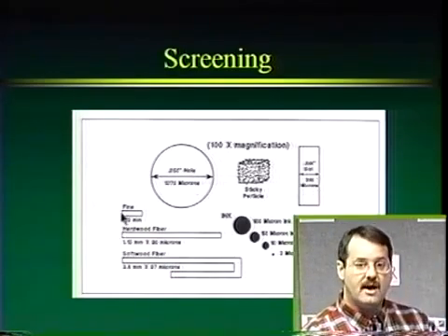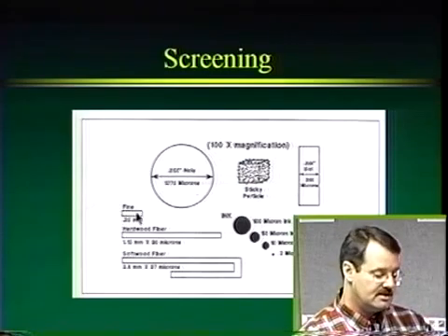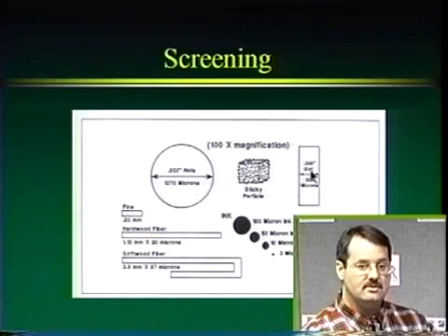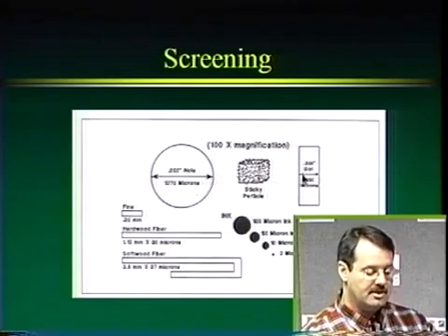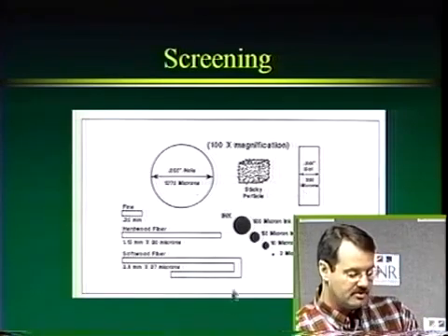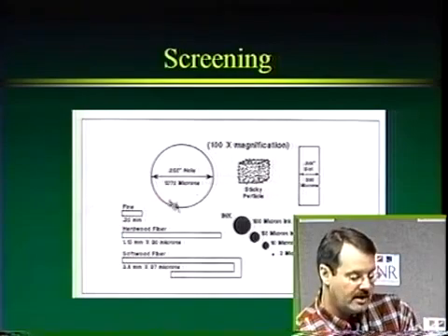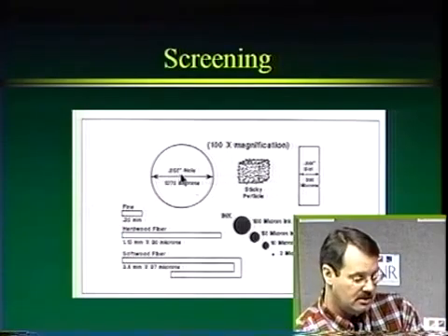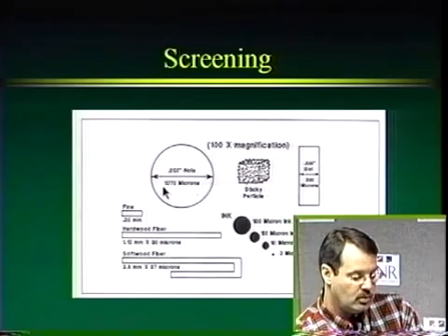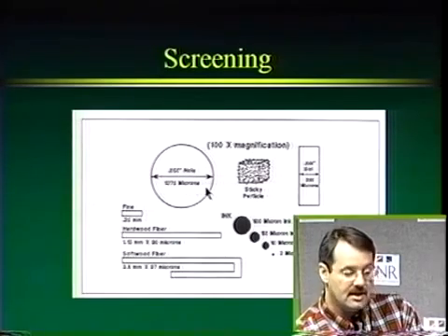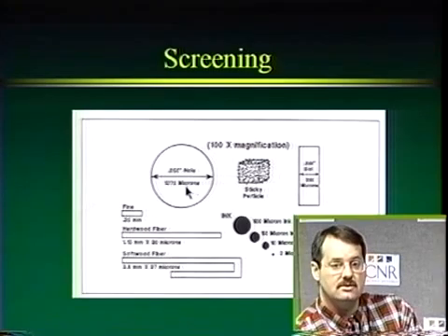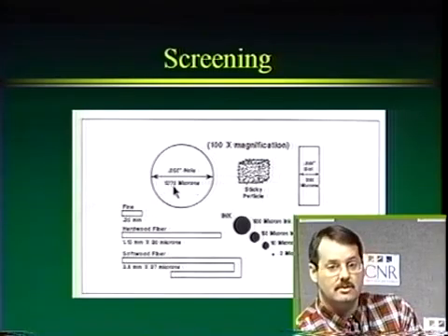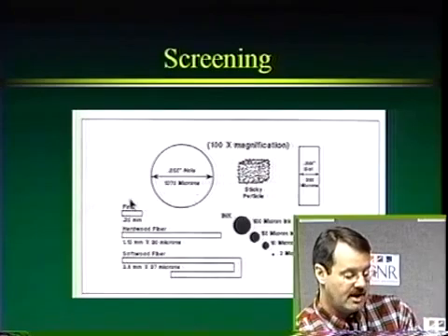And then finally we have the fines, and the fines are usually defined as less than 0.2 millimeters, and that will pass through no matter what alignment it is in. So we can see that all these fibers will pass through this slot. This hole right here is 0.050 inches in diameter, and that's 1,270 microns, and we usually think of millimeters as an easier unit, so that's 1.27 millimeters. And you can see that all these fines and fibers would pass through that hole very easily.